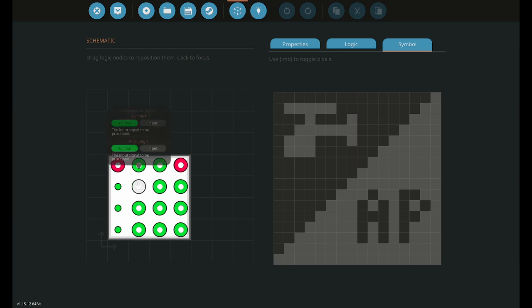Seat pitch comes from your seat. Pitch angle comes from a tilt sensor facing forward. Seat yaw comes from your yaw from your seat. Compass comes from a compass also facing forward. Now the directions for the tilt sensor and the compass are important. If you mess those up, the math won't work and it won't be mathing anymore. And you might end up somewhere, but it won't be at your target.